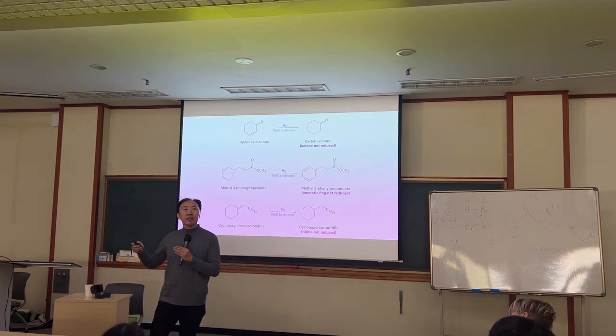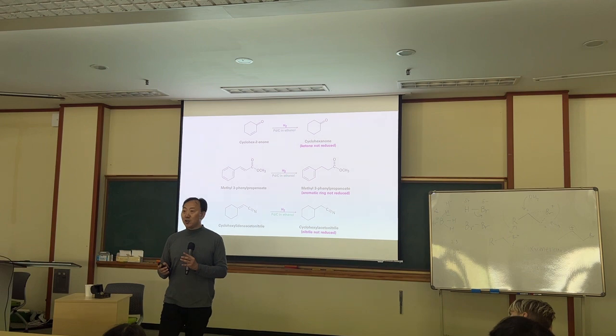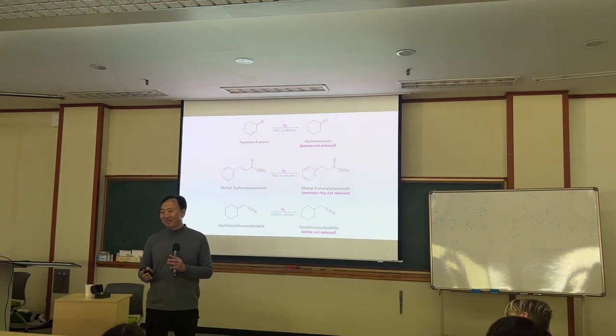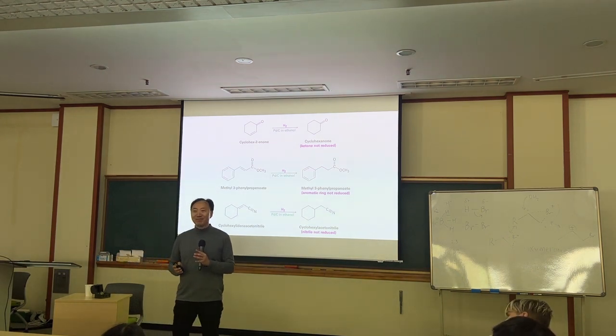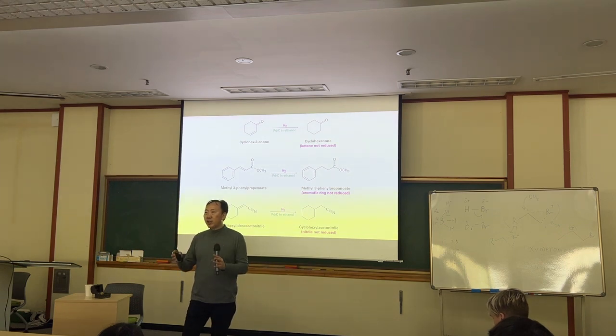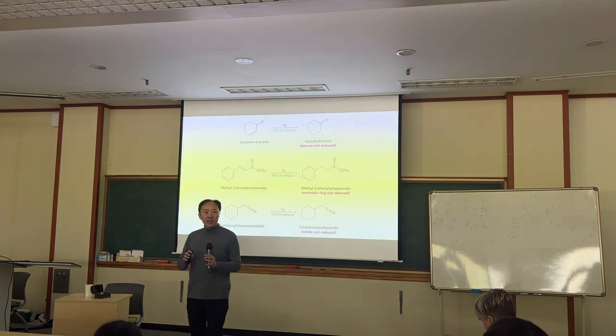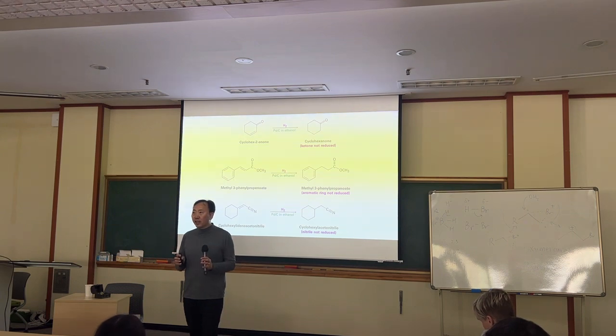If you have dirty air in the room, then usually we have carbon, charcoal, in the room. Yes. Why? Because of the porous structure. In English, porous. If you make the charcoal, then usually we remove all the materials from the inside, so it forms a highly porous structure, many pores inside. With a lot of pores, it has an increased surface area.